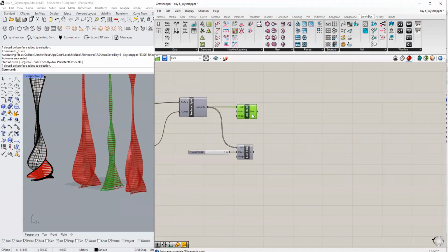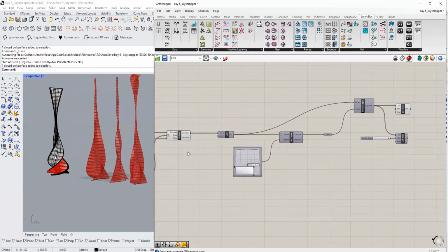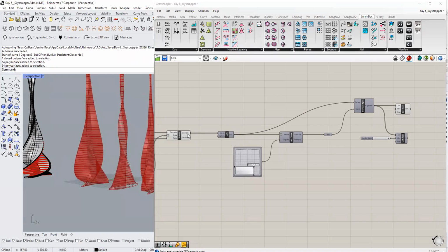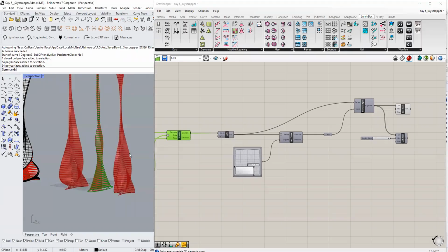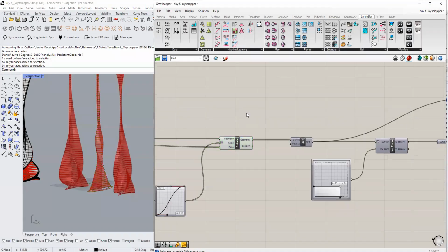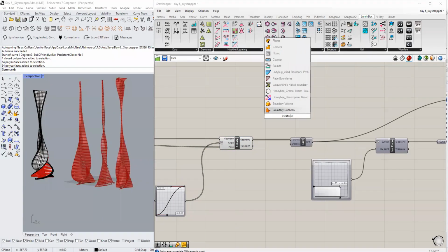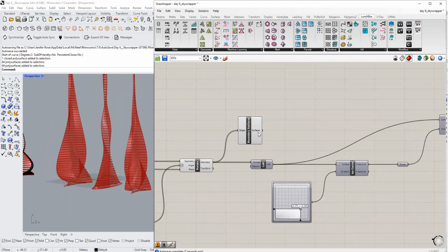And once that is also done, I would like to have the floor plates exposed. Any idea how you would go about creating a surface and adding thickness to these floor plates in Rhino? So these are the floor plate curves. If you were to do these details in Rhino, what would you do? Boundary surface. You can do a boundary surface, that is a planar surface. It will create some surfaces here. To add thickness, we can just do an extrusion. It's a planar surface, and extrude will help us add thickness to it.